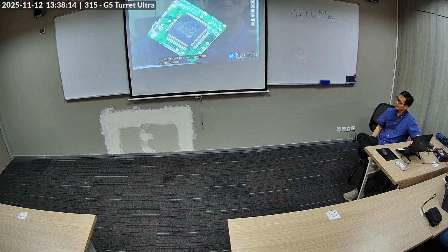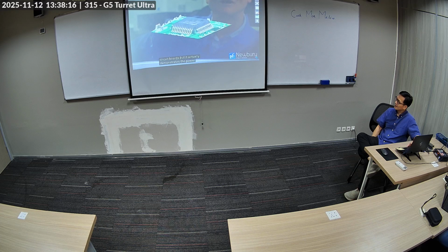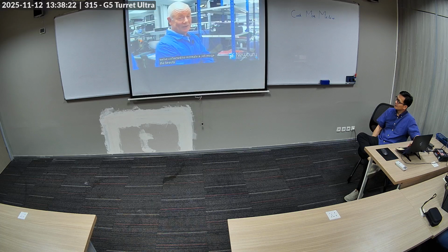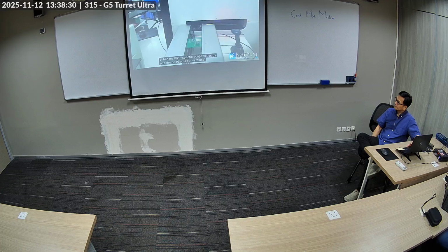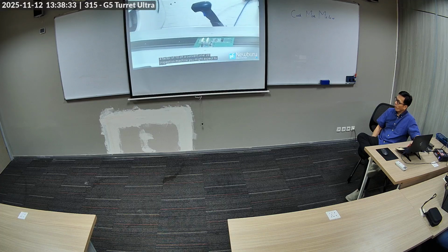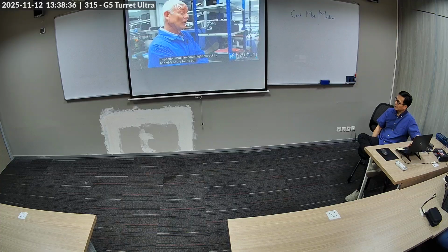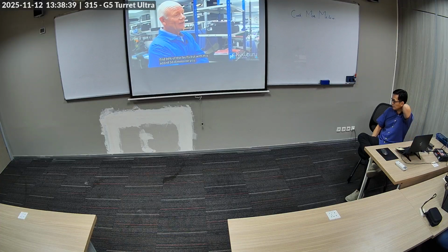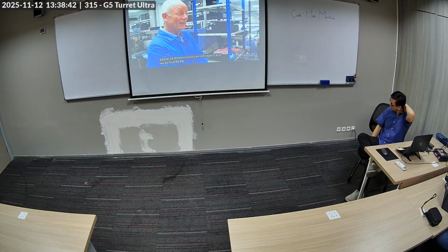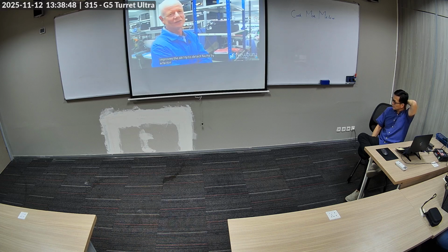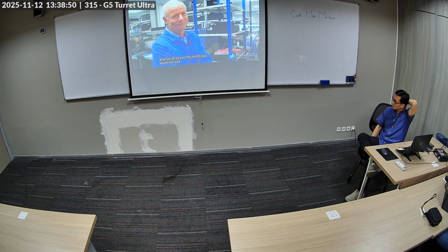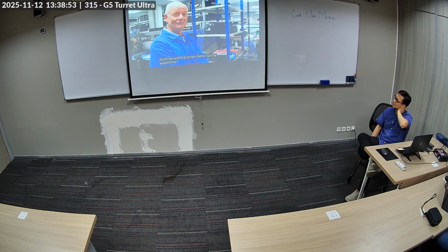Now, this isn't how we inspect the circuit boards, but it demonstrates the power of the data we've collected to recreate a 3D image. The beauty of this machine is that it enhances the inspection capabilities by a factor of 10. On a conventional 2D inspection machine, you might expect to find 99% of the faults, but with this added 3D dimension, you would expect, and we do, find 99.9% of the faults. So it improves the ability to detect faults by a factor of 10 over the traditional machines, and that means better quality assemblies.